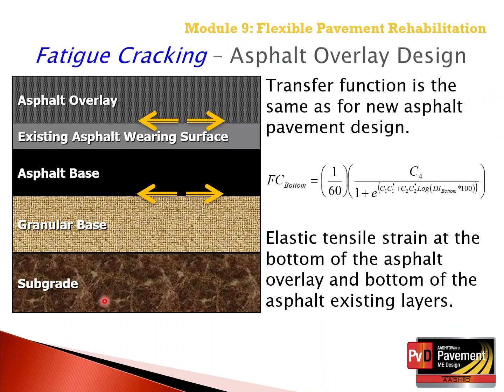So, fatigue cracking in terms of asphalt overlay design for flexible pavement rehabilitation. Bottom-up fatigue cracking: basically, the transfer functions to calculate the bottom-up fatigue cracking in the asphalt overlay and existing asphalt pavement layers are the same.